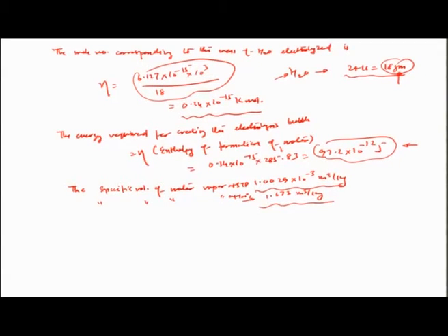So, we want to calculate the size of the bubble and the volume of the bubble, which was calculated before, assuming the radius to be about 14 microns. What is going to be the total amount of mass of water, assuming a thermally actuated mechanism where the bubble gets formed and assuming a specific volume at the boiling point of water, that is 100 degrees Celsius, to be 1.673 meter cube per kg? So, obviously, this is going to be different from the mass of the electrolytic bubble. So, let us see what that difference is.